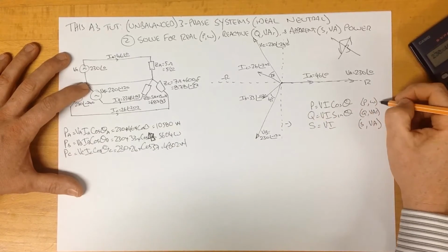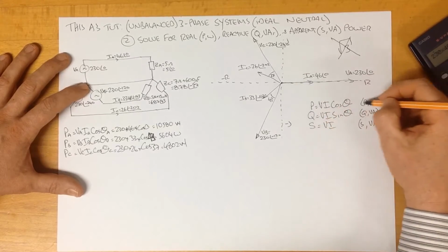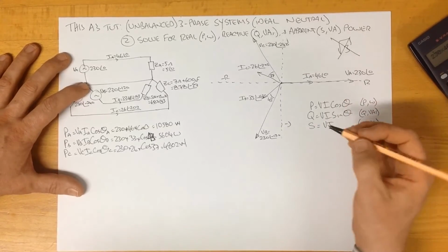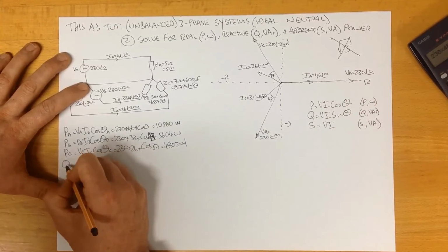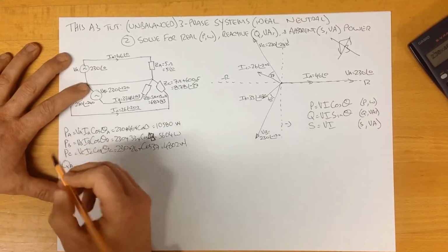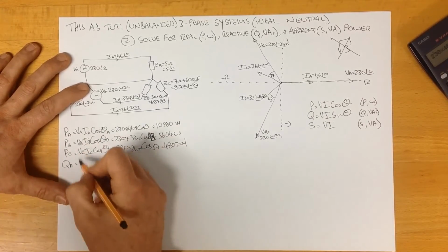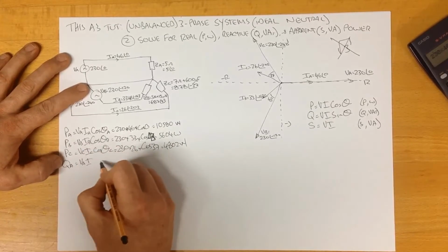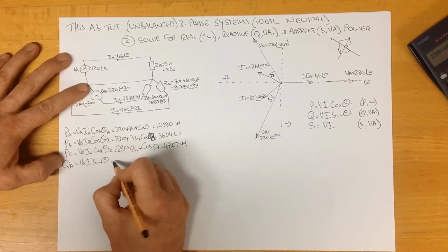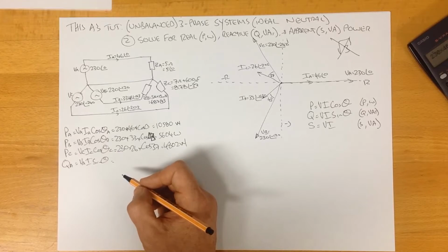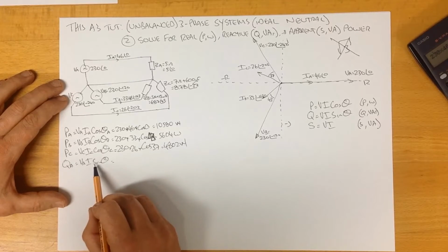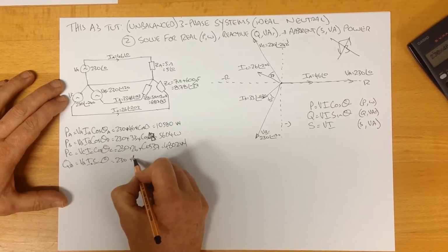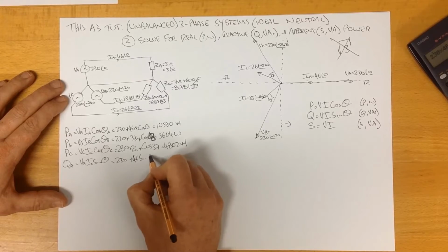So we've calculated the real power dissipated in each of these phases. The real power is how much work is done. Now we can go on and calculate the reactive power. I often confuse those in my wording. The reactive power for phase A is VA, IA, sine of that angle, which is 230 times 46 times the sine of that angle.